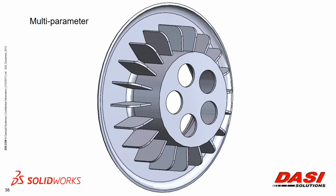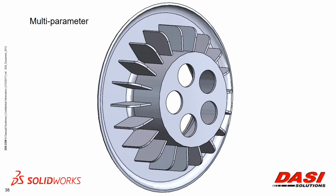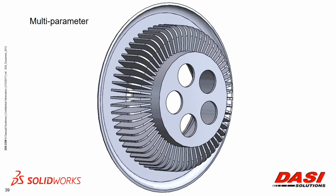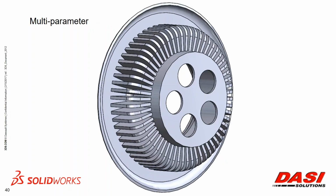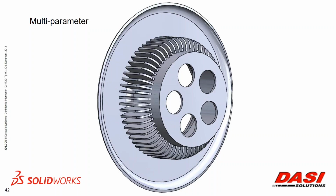So some of the variables I'll be playing with in a moment is just going to be the number of fins. Okay, so like I think 20 fins here versus 60. The thickness of the fins will be another variable. So it's adding a lot of extra mass, but it is adding a lot of extra bulk heat that will be allowed to transfer to the fins. So I'm not sure if this will be better than that or not. So we're going to experiment with that, and then also the fin depth.